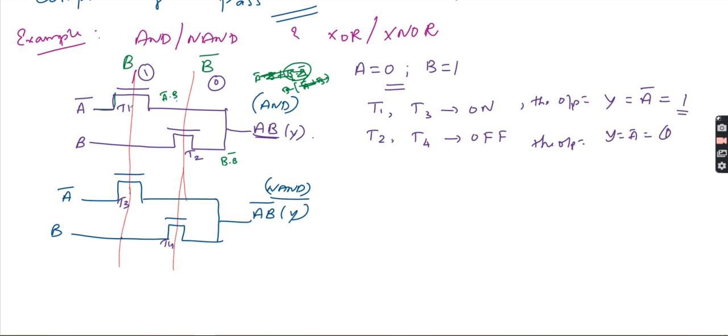When I use this kind of circuit, load capacitance will be there. Then we can use this for adders and multipliers. The main advantage of this design style is that differential output signals are available here also.